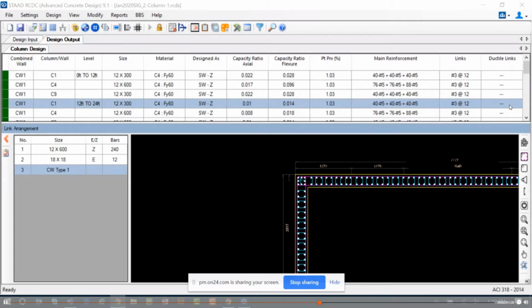One area. So we're going to notice that this is being designed as a combined wall. So automatically, I created a finite element mesh in STAAD.Pro, where I had basically 2 meshes intersecting each other at 90 degrees. Technically, if I were to take a look at the 3D view in STAAD.Pro, I'd see that the center lines of the walls are basically joining up. So automatically, the RCDC has filled in the rest of this wall. It's not just center lines joining up in, say, a missing piece of concrete. It automatically created that corner for me.